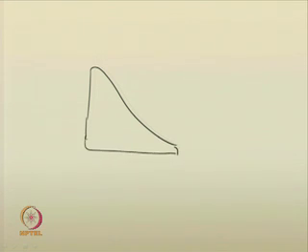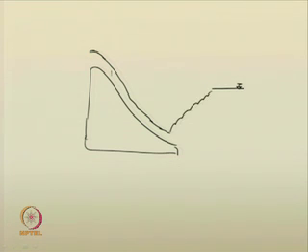Another example you can see is if there is a spillway, and the downstream has a certain depth of water. Water flows over a spillway at a high speed and at a low depth along the spillway, and it reaches here. See the depth here, it is very small, but in the downstream we have a larger depth. This change in depth causes a hydraulic jump.